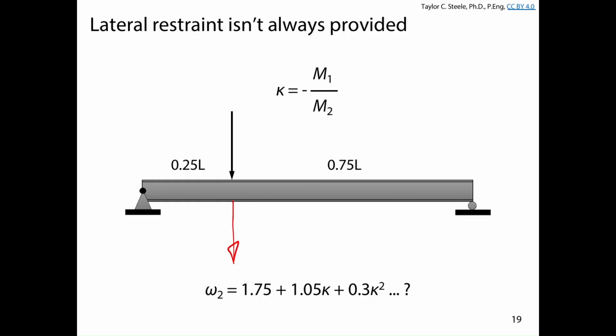The right answer is no. You can't. I guess you're just literally hanging from a rope. You can't prevent it from resulting in lateral torsional buckling. And so it's quite common for the design of monorails, for example. A monorail is a little beam that has a trolley that basically has a hook on it and carries heavy things from one side to the other.